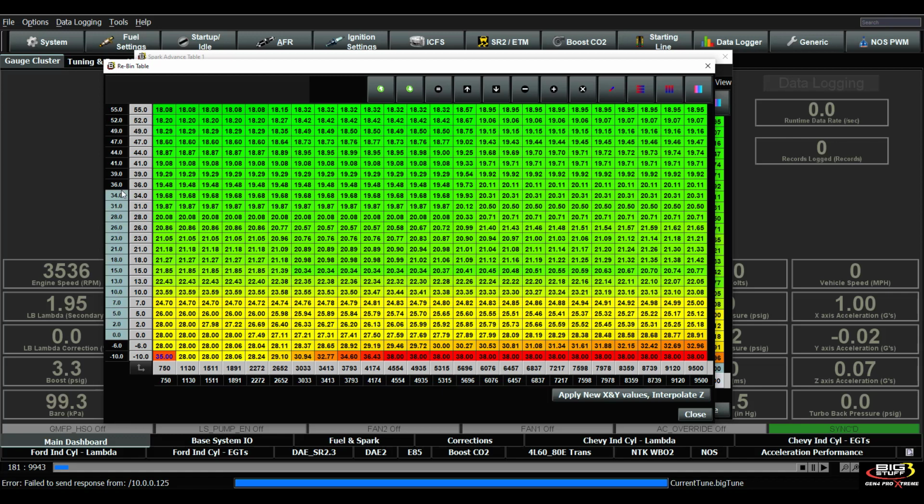We want a lot more resolution there. So you would just simply go from 0 to 55 pounds. You would highlight the row, right click, and then interpolate the selected cell values. Then just to make it a little cleaner, I like just putting a .0 at the end instead of having the .2, .8, whatever they typically may come up with when you interpolate.